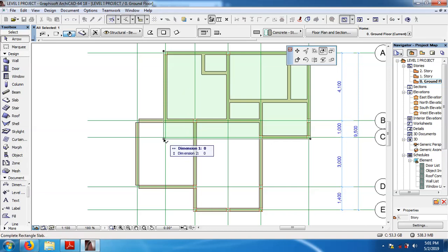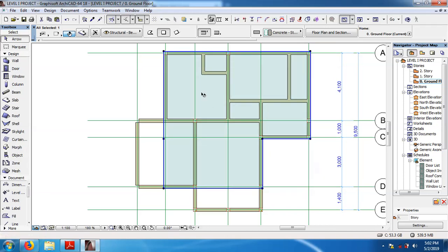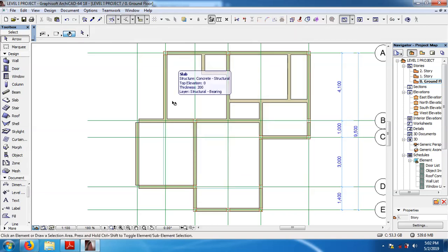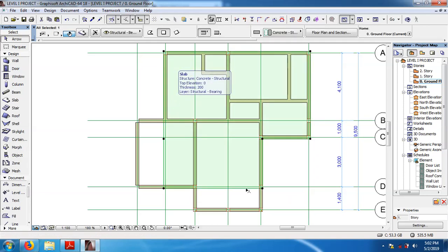You click this node, and then you draw it, fit it right there. Then you click. What do you notice? The slab just extended. So we do not have two independent slabs here, only one slab that assumes the shape. Do it again. We want to extend it at this point and at this point. So click it. Make sure you pick this command, add to polygon.